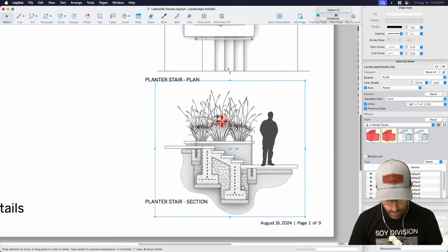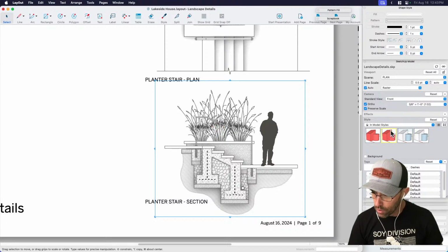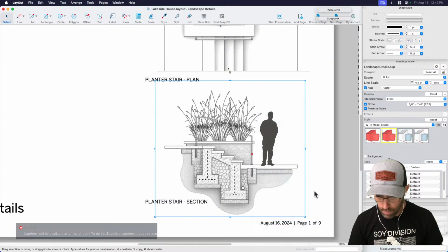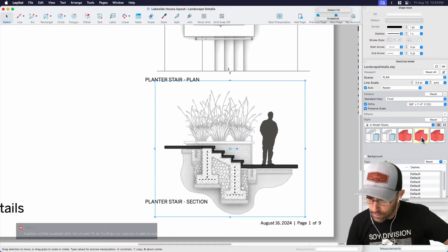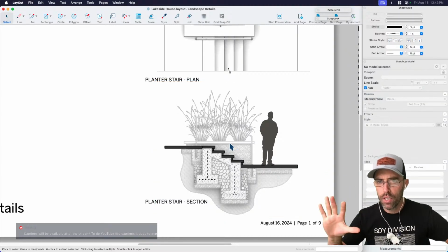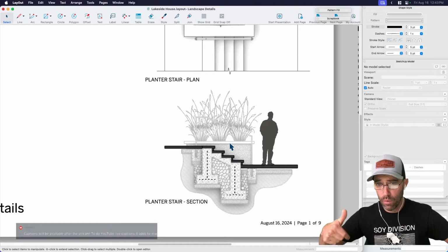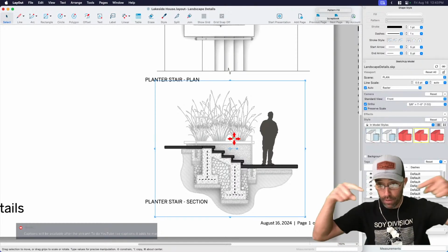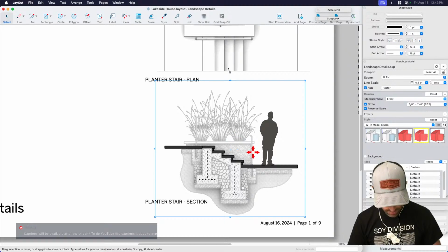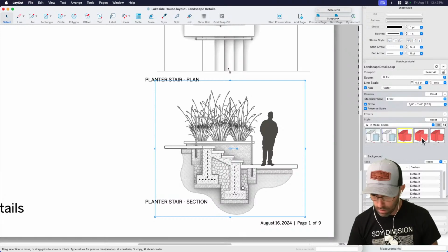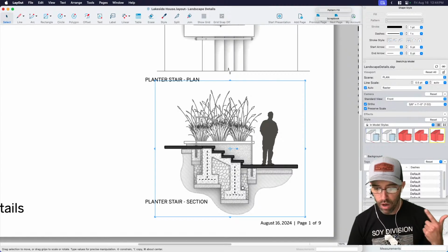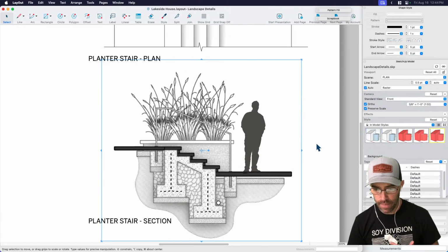I'm going to copy this viewport, and then update my model reference. You can see that new style just came in. If I go to my new style, this one is called fade, you can see it's now pushing the plants to the background. But if I want the footing and the handrail to be a little more detailed, I can put that back to the foreground. And then I can turn my plant symbol off. Do you see that, Matt?